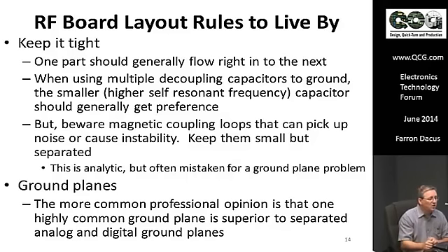It can also be visualized, and if you can see where your current loops are, you can actually approximately calculate these things and see what is the coupling through this transformer mechanism that's set up by single loops in the layout, and how can that lead to instability. Another place I've seen these magnetic coupling loops cause a real problem is coupling in the noise of, say, switching power supplies.